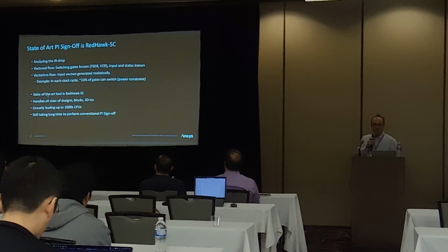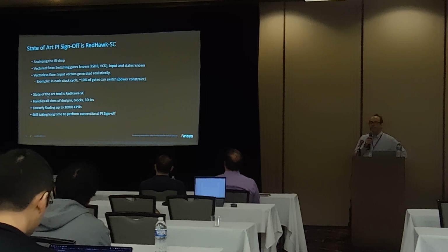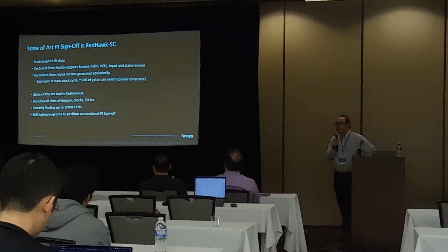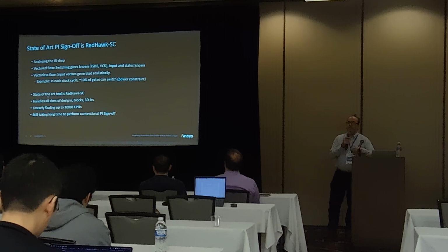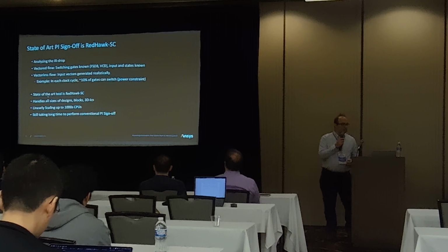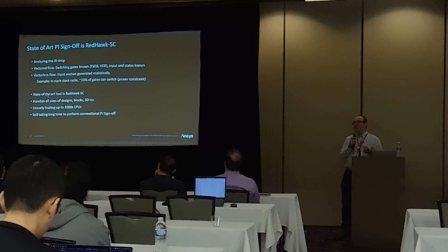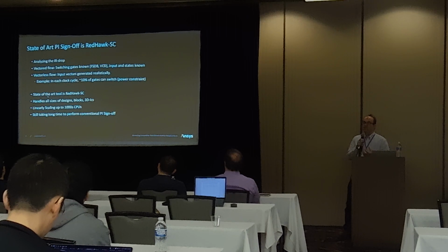So the state of the art in power delivery and power sign-off is that we have a couple of tools, and our tool is called RedHawk. This has gone through a decade of innovations. First we started with static analysis, then dynamic analysis. Typically, we analyze IR drop on transistor gates: the voltage and ground that the gates see, based on which the performance of the gates will differ and the timing will be different.